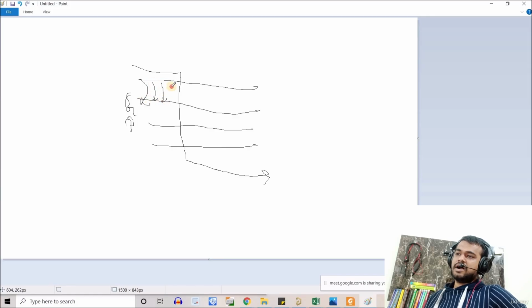It will start returning the current because of coupling. Now when we change the layer, the return path will go to layer 3 first, which is the power, and from layer 3 it will couple to the ground.